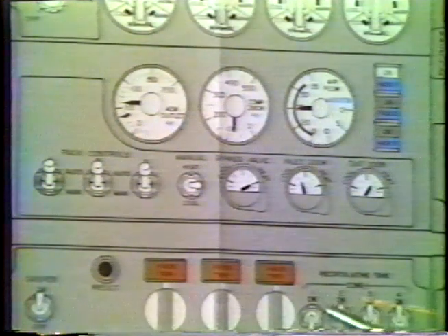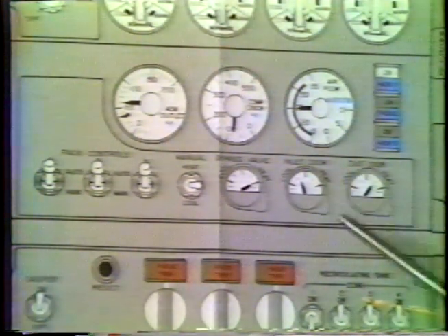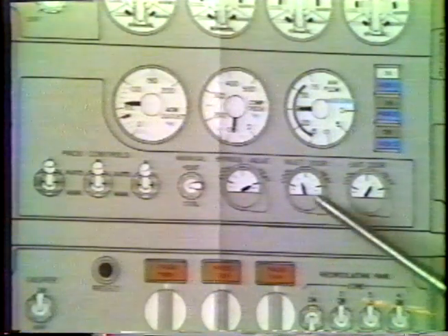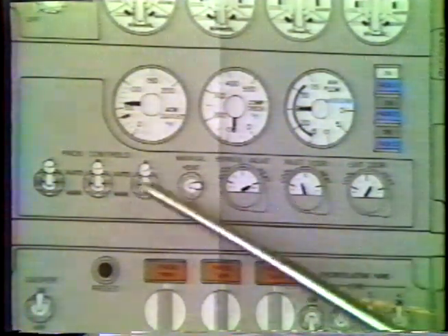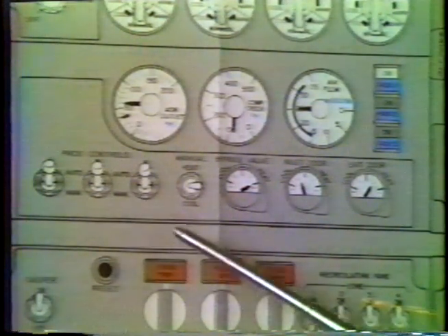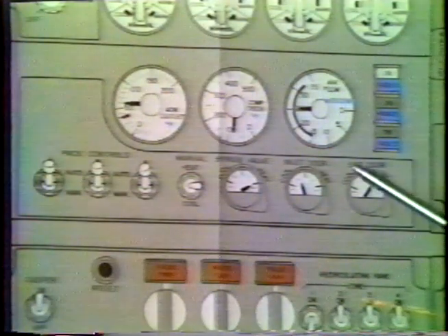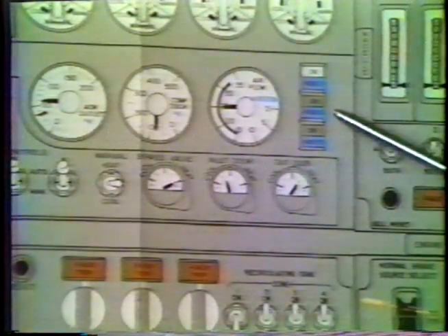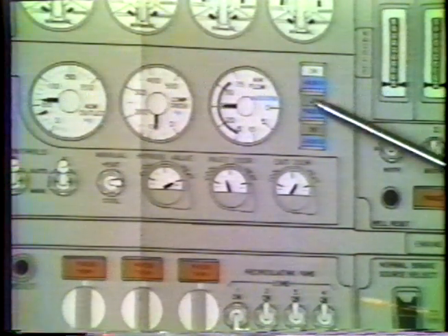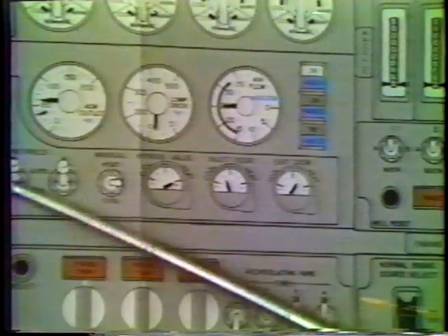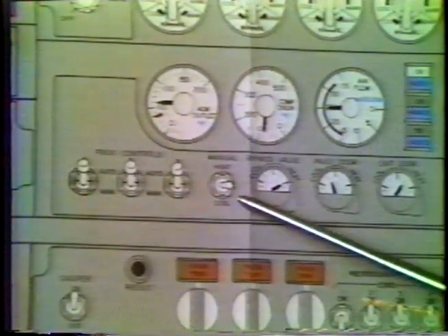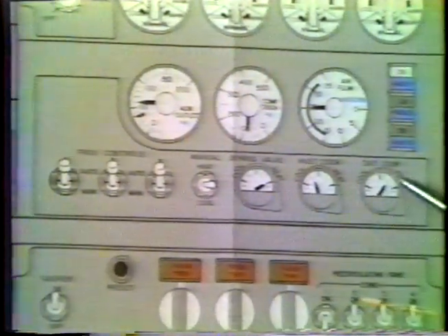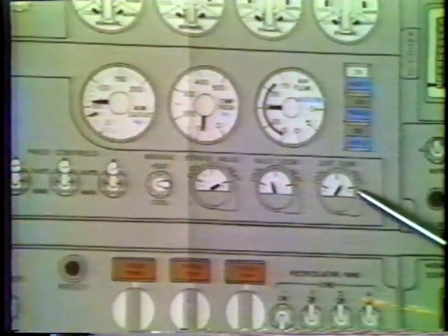Sometimes the operation of the bypass valve and the inlet door, which is controlled automatically by a small computer, doesn't work properly. If that's the case, the pack can be operated in manual. To operate a pack in manual, however, the pack that you want to operate in manual must be selected with the push button. For example, if you want to operate number 2 pack in manual, you must push the push button for number 2 pack and then move the pack selector to manual, and then with the use of the toggle, you can operate the bypass valve and the inlet door. No operation of the exit door is available in manual operation.